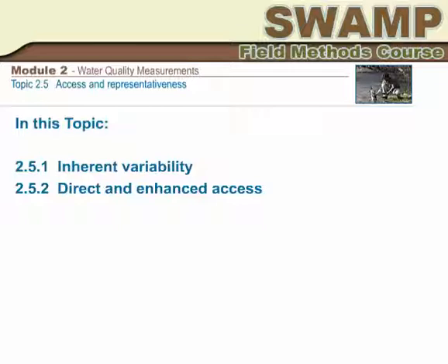One of the main challenges field operators face is to find the centroid of the flow, which is the line that separates the flow discharge into two equal parts. It is often the most representative spot in the channel. There is more information on centroid flow and stream habitat types in Module 4, Section 4.1.2 of this course. To read more about the subject of representativeness, please visit Common Element C of this course.